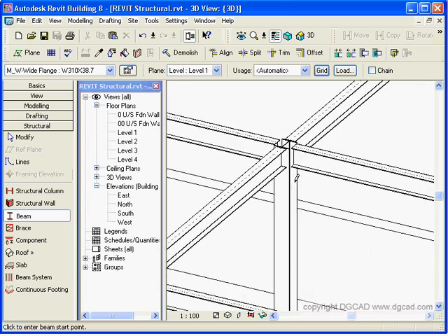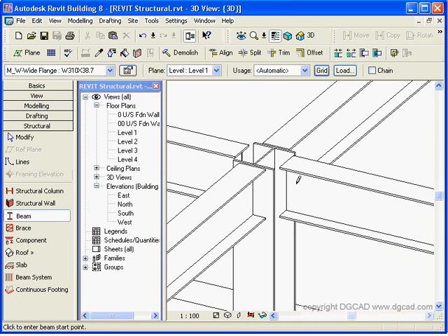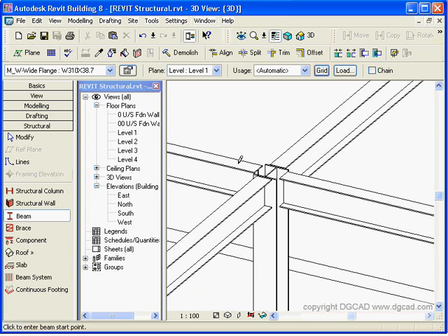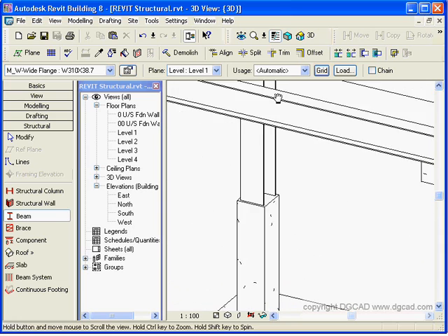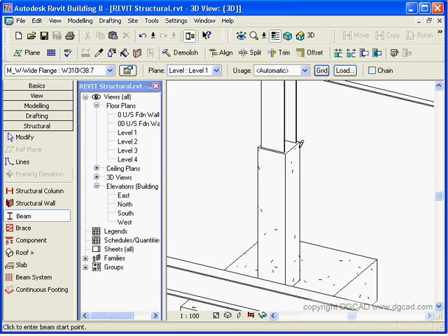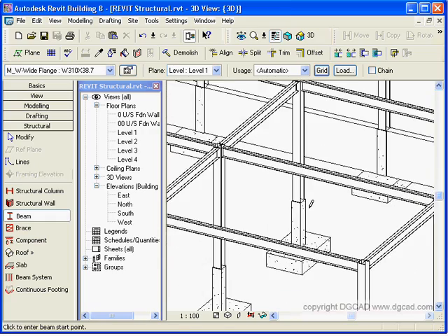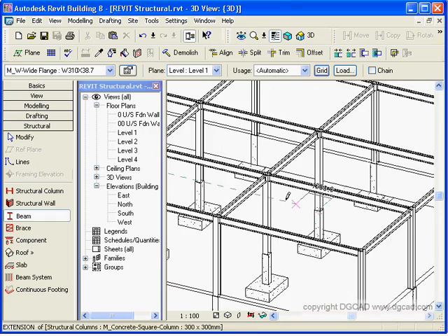And with Revit Structure, we have connection clips and base plates and anchors. With Revit Building, we don't have the connections or families built in. When you use Revit Structure, you can put clip angles and you can put base plates down here at the bottom where these columns hit these piers. So then we've got our second level done.